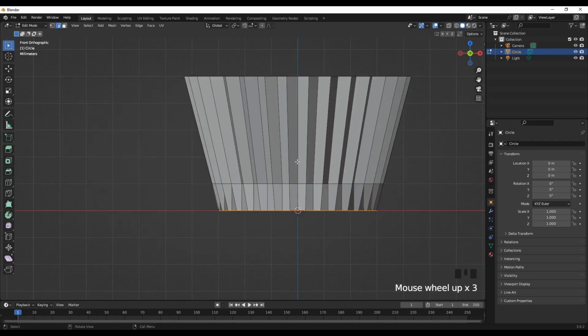Here you can see I have a line, but in this part there is no horizontal line. So for appropriate mesh structure there needs to be a line. For this, move your cursor somewhere here and press Ctrl R. This brings up the yellow line.